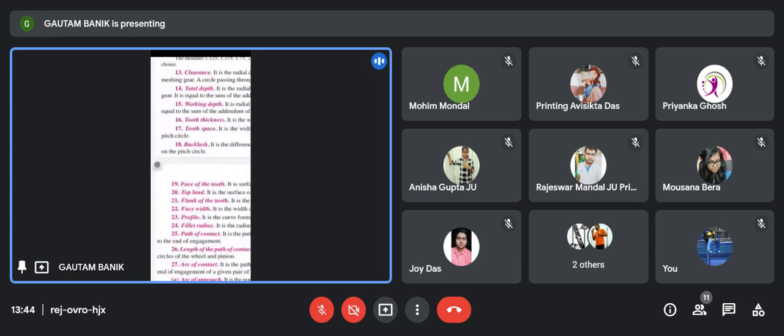I will show you the picture; I cannot do it right now, later I will explain again. The backlash. When you start the gear drive, when you switch it on, the driver is rotating, but the driven gear is not rotating. There is a gap. When the backlash distance is made up, then the follower will move. So this part is called the backlash.